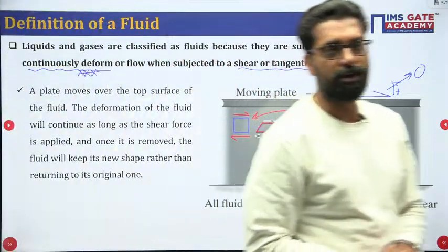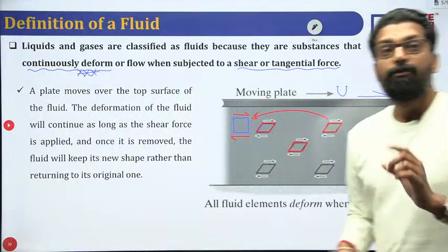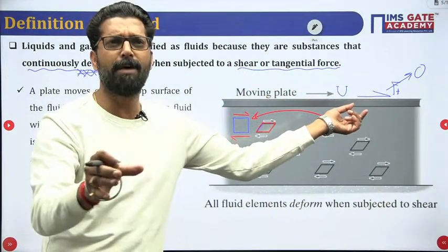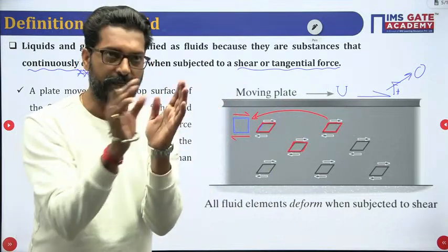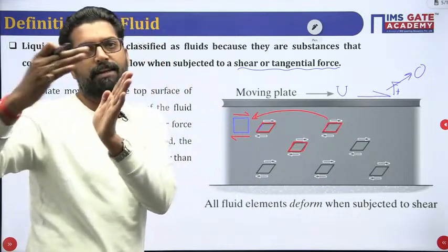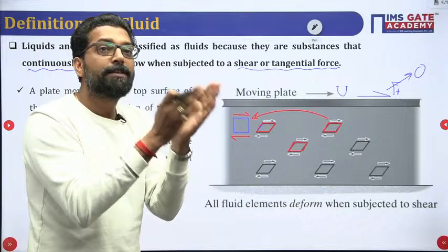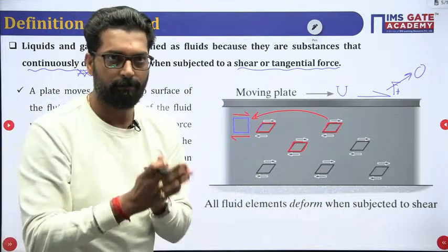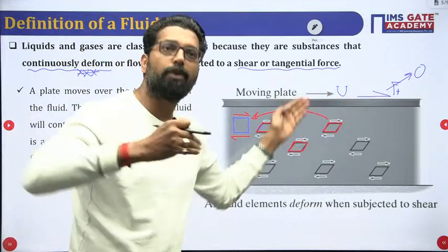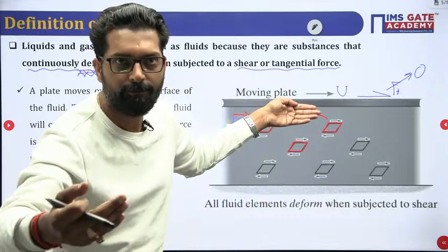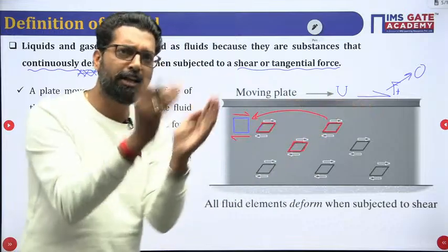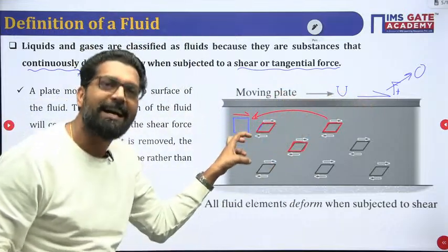Yes, very good question, Saurabh. Fluid always deforms by the external force. What is the minimum force? There is no limit. See, your question is, if there is a solid and there is a fluid, solid deformation requires a certain tangential force. In the case of fluid, a tangential force is also required, but it does not depend upon the magnitude. Whatever the tangential force, the fluid tries to deform.